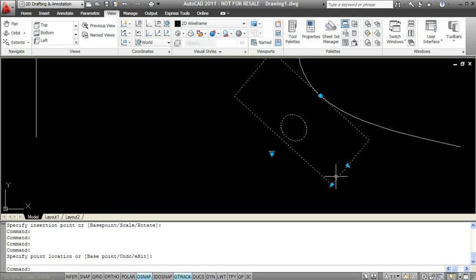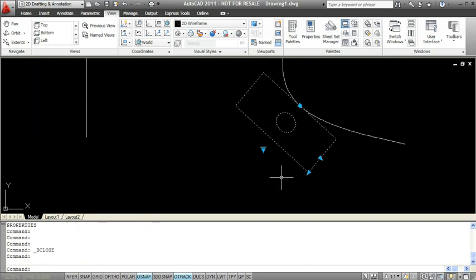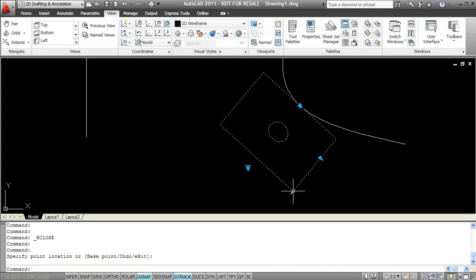Now you may notice that my basin is not staying centered, and that's because it's actually moving with my grip, if you remember from the definition. So if you just go back into the definition and you change the multiplier for that move action, you can actually get the basin to stay centered in the counter. So for the sake of time, I've gone into the block editor and I've done that, and now you can see as I move this out, my basin stays centered.